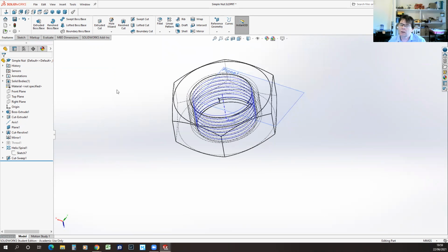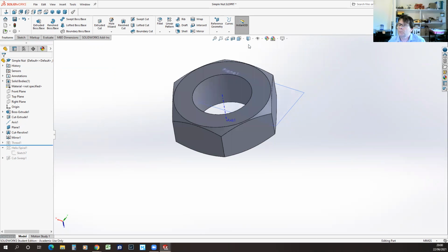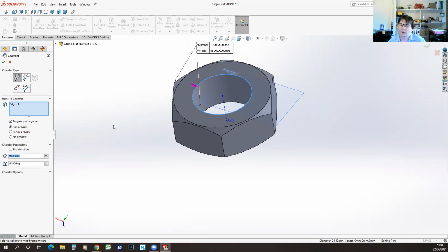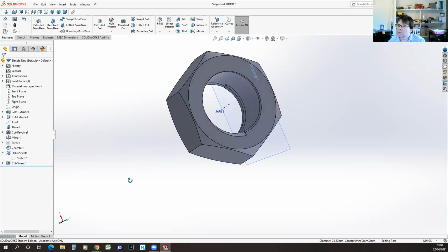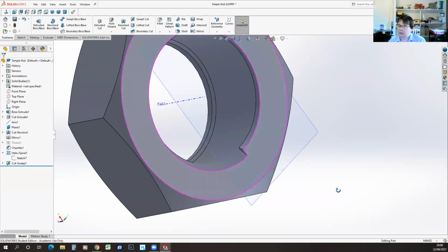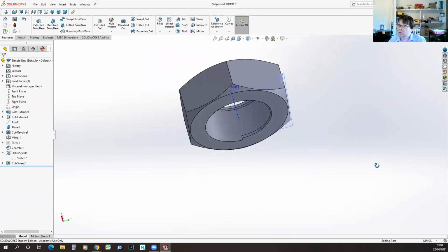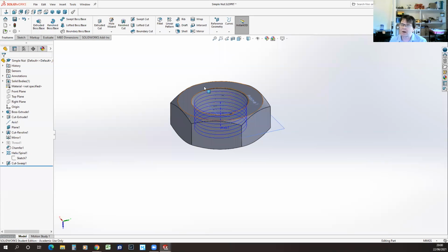What I did for my part was, before I defined my thread, I actually put a chamfer on this surface. I think it's a millimetre. And that just enabled my thread to start cutting in. Doesn't look quite as neat as the one that I designed before, and for some reason it's not drawing the internal lines, but that's the principles of how I made the thread.